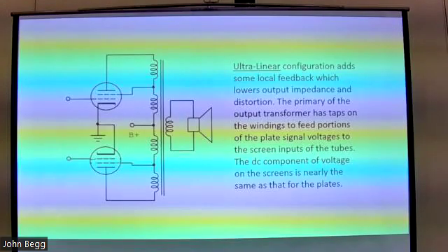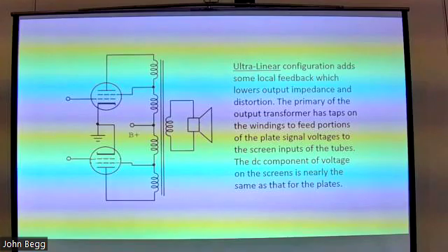But yeah, this is part of the game when I was talking about the two equations: balancing those equations so that you maximize your power transfer. And there are a lot of factors involved. One I just sort of glossed over is that you don't have zero output impedance on your 6V6, and you don't have infinite this and infinite that.